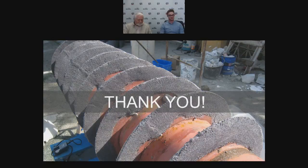Next question. We have John Paul from Berlin who is asking, we have a screw conveyor handling ash and bark. We use hard face welding. Would Belzona be a good alternative? It's a difficult question, that. We do quite a lot of screw augers, and our materials are extremely good at protecting the shaft and the face of the screw threads themselves. On the edges of the vanes, you generally find hard face welding.